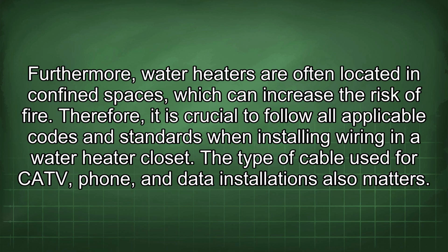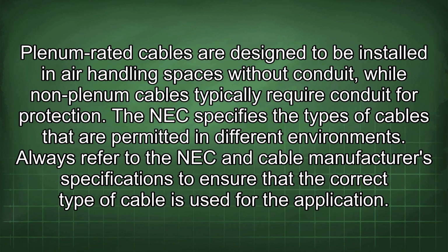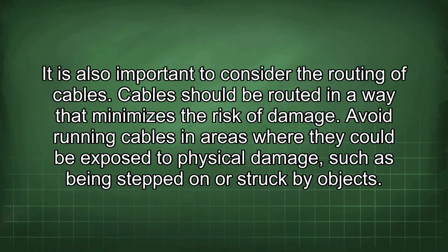The type of cable used for CATV, phone, and data installations also matters. Plenum-rated cables are designed to be installed in air-handling spaces without conduit, while non-plenum cables typically require conduit for protection. The NEC specifies the types of cables that are permitted in different environments. Always refer to the NEC and cable manufacturer's specifications to ensure that the correct type of cable is used for the application.